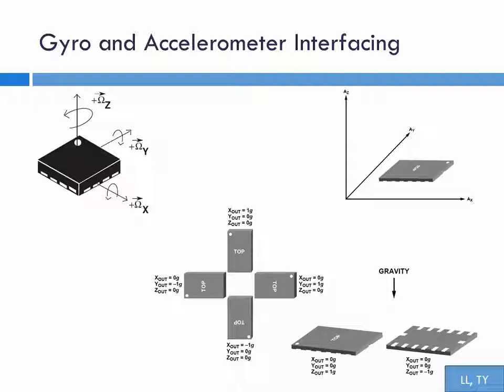On the right, we have the motion sensor ADXL345 used as the accelerometer. It measures the gravity vector of each axis. Note that a measurement reading is always opposite of the gravity. Take the upper view of the 4 position drawings for example. Gravity is pointing straight downwards, with the y and z planes perpendicular to it. So y and z readings are always 0, whereas the x-axis is pointing exactly in the opposite direction of the gravity, so it has a reading of 1g, not minus 1g.